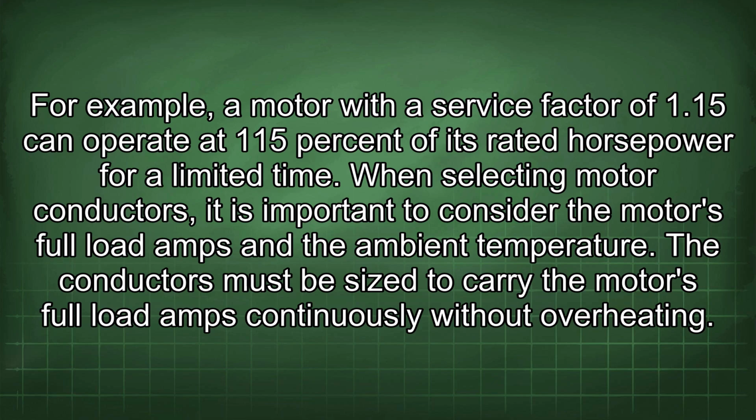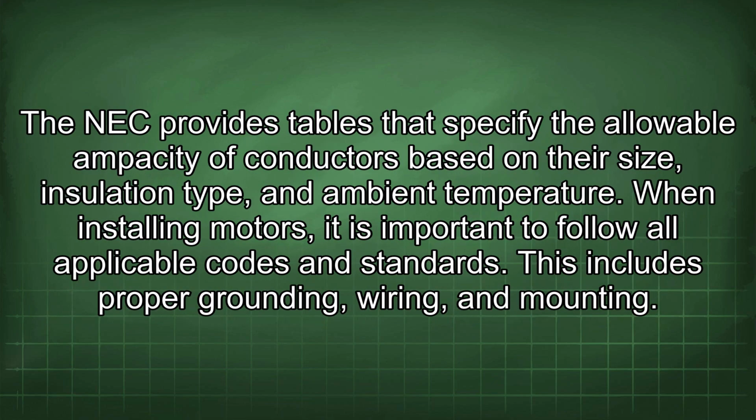When selecting motor conductors, it is important to consider the motor's full load amps and the ambient temperature. The conductors must be sized to carry the motor's full load amps continuously without overheating. The NEC provides tables that specify the allowable ampacity of conductors based on their size, insulation type, and ambient temperature.